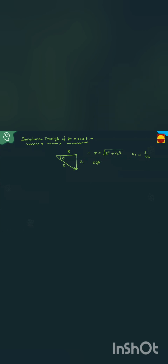What is cos theta, students? That is the power factor. This is equal to R by Z. What is tan theta? This is an important formula. In an RC circuit, XC by R. In an RL circuit, XL by R. Then theta equals tan inverse XC by R.